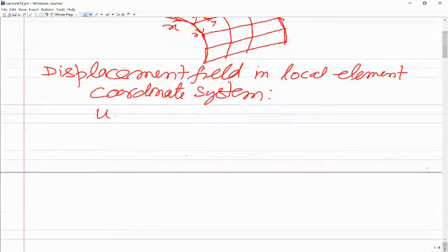So now, as I said, because different plate elements are in different planes, the bending displacement of one plate element will cause the in plane displacement of the middle surface in the other element. So we need to have the in plane displacements in the theory.